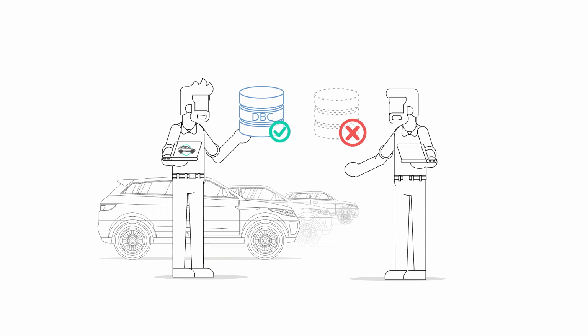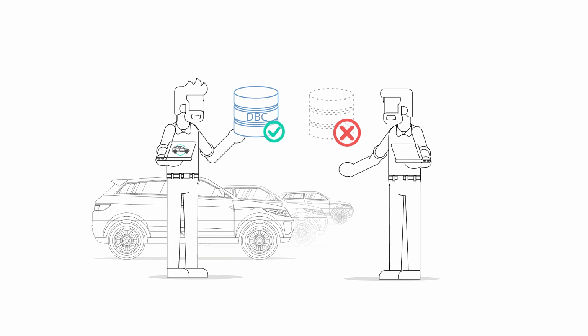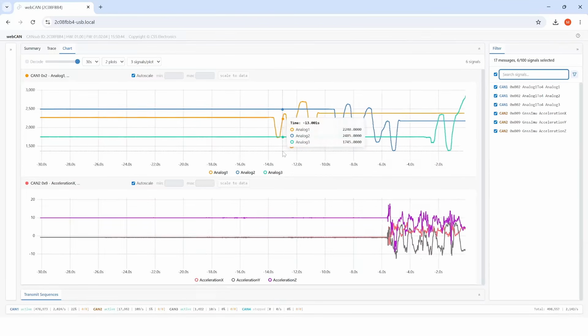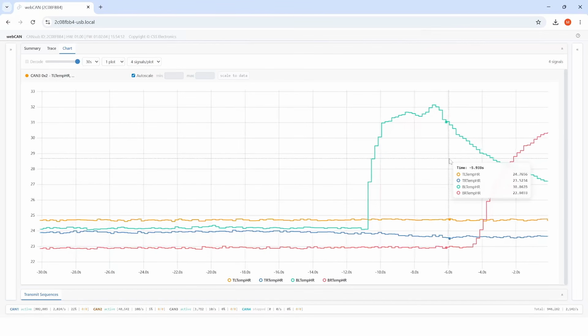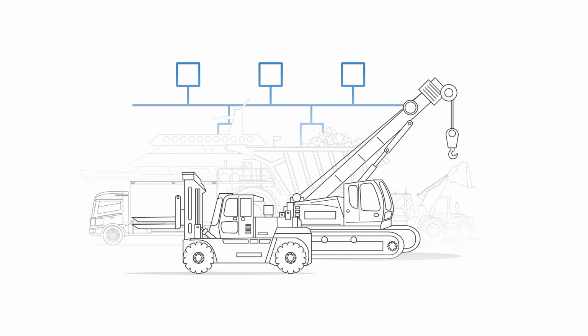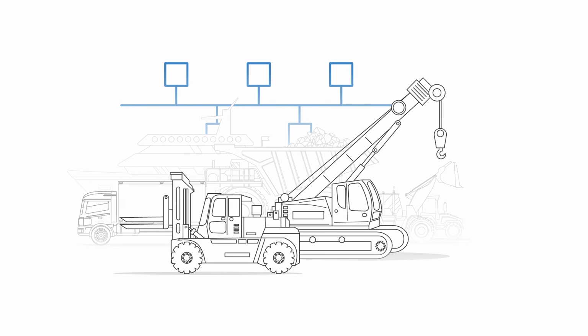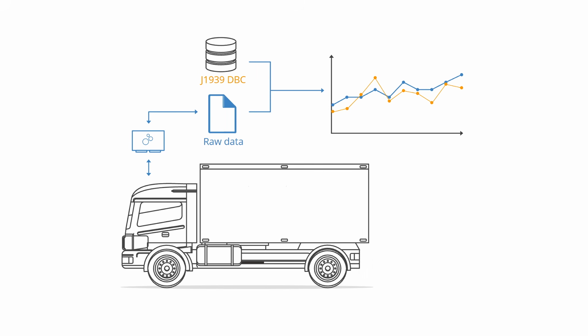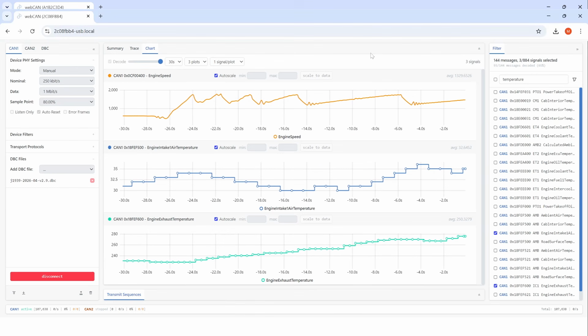Only the manufacturer is able to say how to go from the raw CAN bus data into what we call physical values, meaning the decoded and scaled signals such as speed in kilometers per hour, RPM, temperatures in degrees Celsius, and the like. Now, there can be some exceptions to this rule. As an example, in the heavy-duty world, J1939 is a standardized protocol that is used by most manufacturers, and as a result, you will be able to decode a large share of the data that you find on an average truck if you buy a J1939 DBC file.